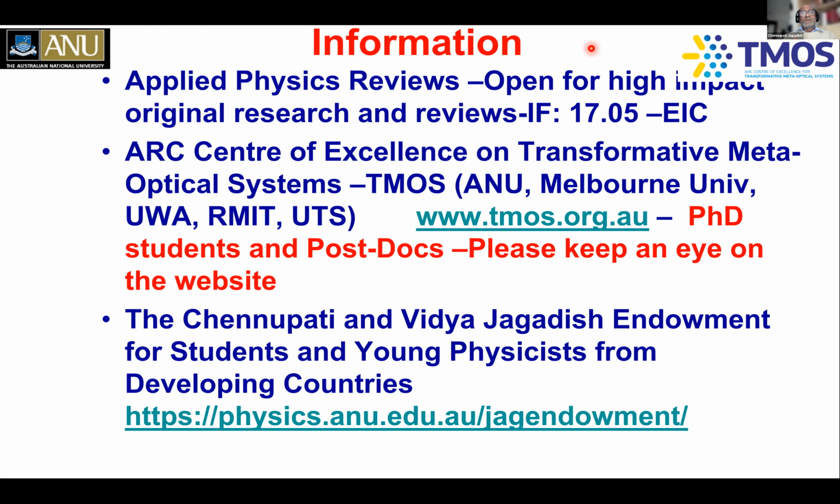Sometimes we remove the nanowires which are grown vertically from the substrate and transfer them onto a glass substrate to be able to make contacts and other things. Sometimes we make use of these. For example, if I want to make more efficient solar cells, keeping them vertical is good because you're able to use light funneling effects. So it all depends on what applications you have, and then you choose either vertical or horizontal nanowires.